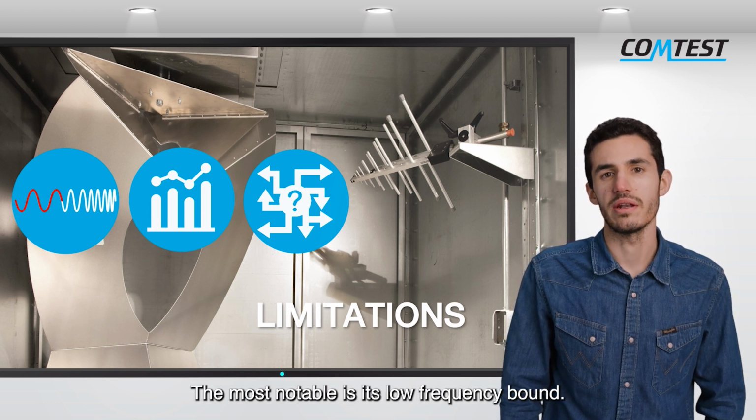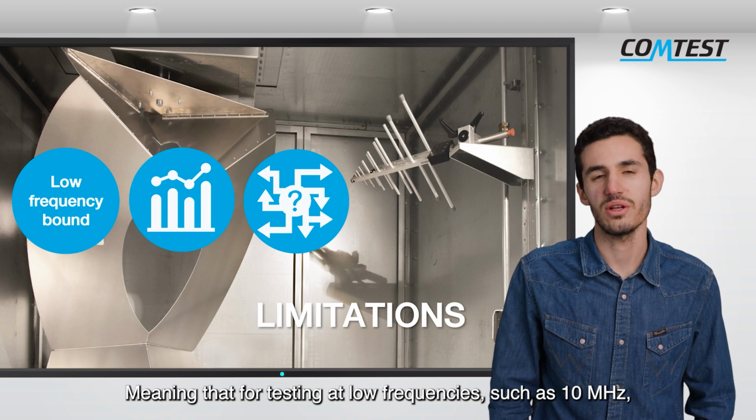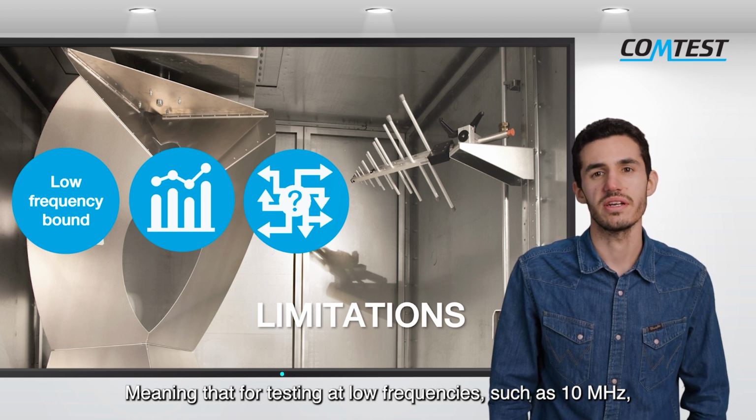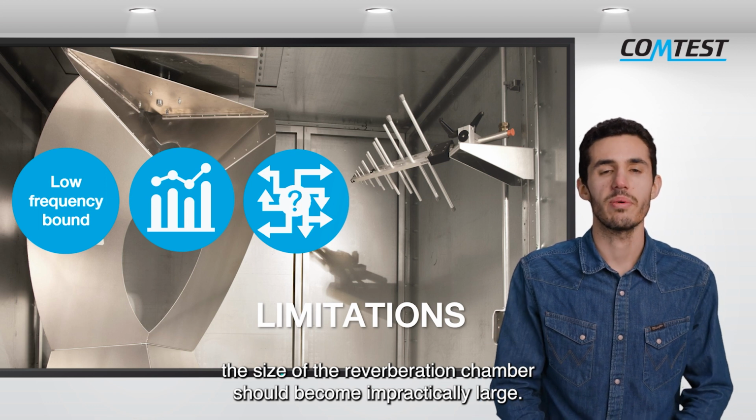The most notable one is its low frequency bound, which can be approximately as low as 50 to 80 MHz for a big chamber. The limitation occurs because the resonant frequencies of the chamber depend on its physical dimensions, meaning that for testing at low frequencies, such as 10 MHz, the size of the reverberation chamber should become impractically large.